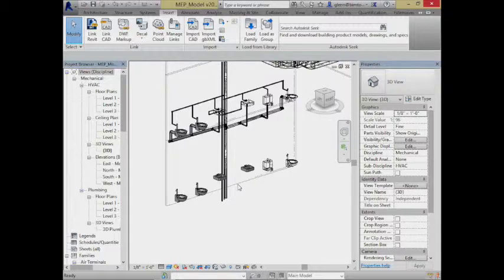And then all these wastes, we could try and run individually over to a sewer somewhere, but we don't do that. What we tend to do is bring them all together into something I'll call a lateral of some type that brings them all into a single line and carries the waste away. And as we think about that line, we don't run it laterally, at least in terms of having it perfectly flat. If we did that, we'd have a problem. Ultimately, the waste wouldn't flow downhill. So what we do is introduce a little bit of slope. So we'll be heading on down.